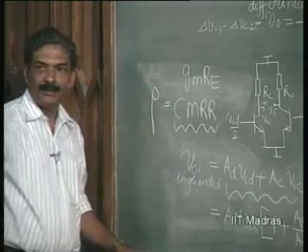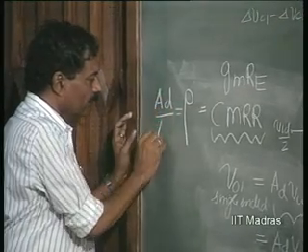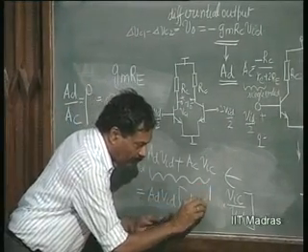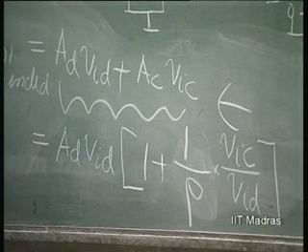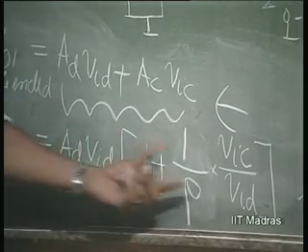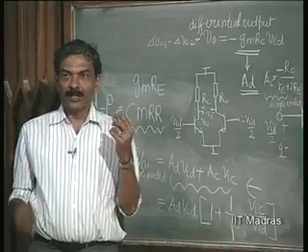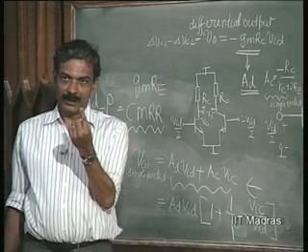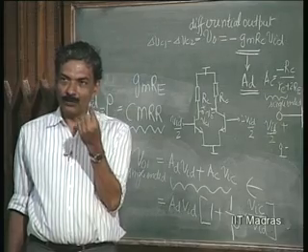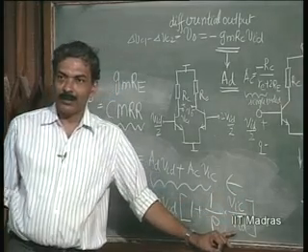This is normally assigned the symbol rho. So, AD over AC, this is nothing but rho. Therefore, we see that this error is 1 over rho. Now, you can see the significance of this differential amplifier analysis lies in estimating this error. Let us assume that VID is of the order of 1 millivolt. I have differential voltage of the order of 1 millivolt superimposed over a common mode voltage of 1 volt. So, this is 1 millivolt, this is 1 volt. That means, this factor VIC by VID is already of the order of 10 to power 3.